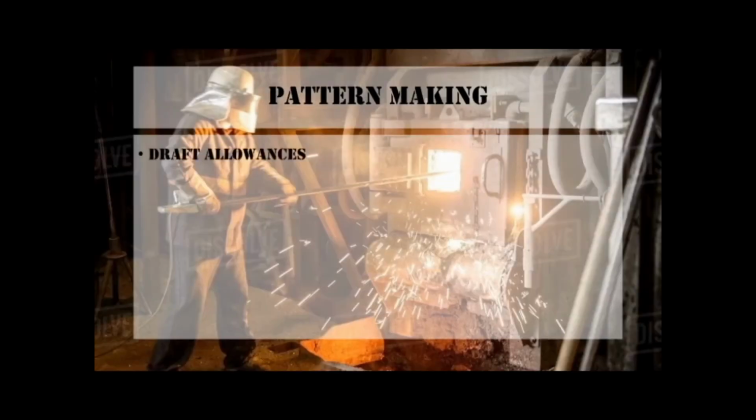Second one, draft allowance. It is a taper given to the vertical walls of a pattern for easy and clean withdrawal. By providing that, we can remove patterns without damaging the mold.